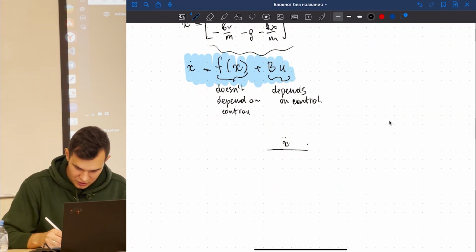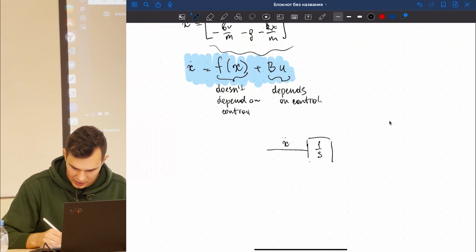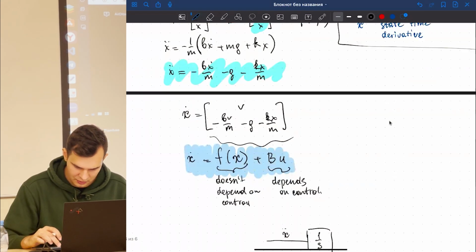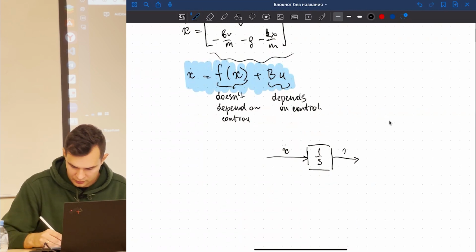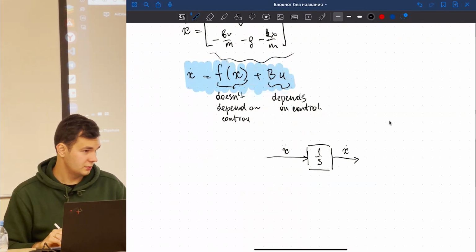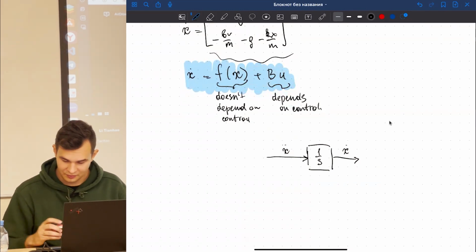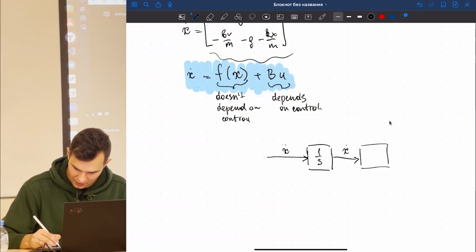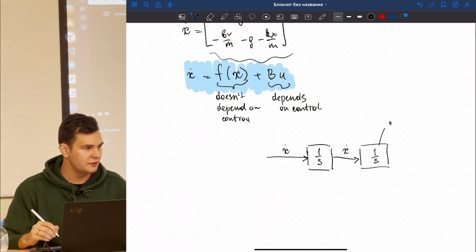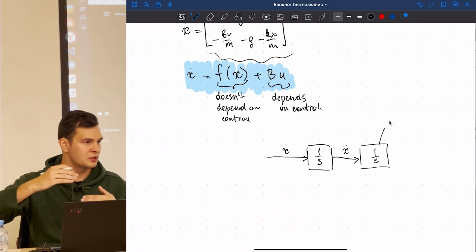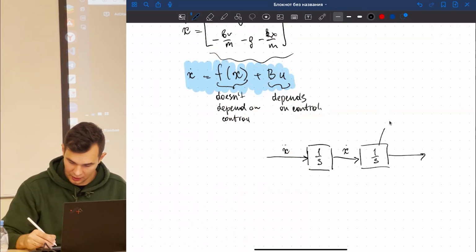Yeah, you need to use an integrator, and there is a block in MATLAB that integrates the system and spits out velocity. What should I do in order to get position? Yes. And inside it, you can give the initial position, and it will be like a deflection of your spring. And here will be position.